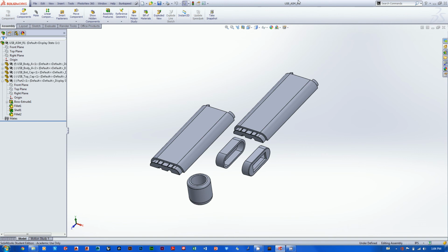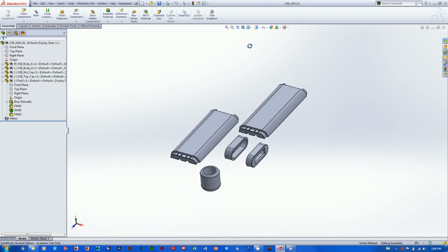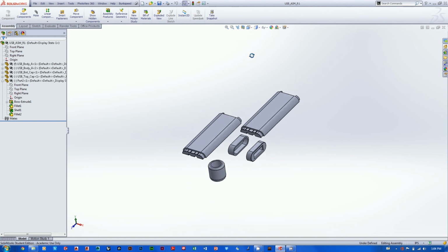kind of like security measure, we'll call it, that SolidWorks gives you when you are dealing with an assembly that has virtual components in it. So as you try to save that assembly file, it's going to say, hey, you've got stuff in here that's just purely virtual. Are you sure you don't just want to save a part file as well? And so it's going to catch you at the last minute. So keep your eyes peeled for those warnings. And if you see any of them come up, then you know what you've got to do.